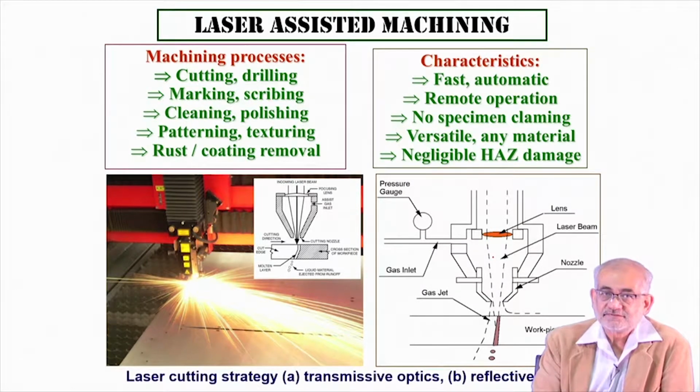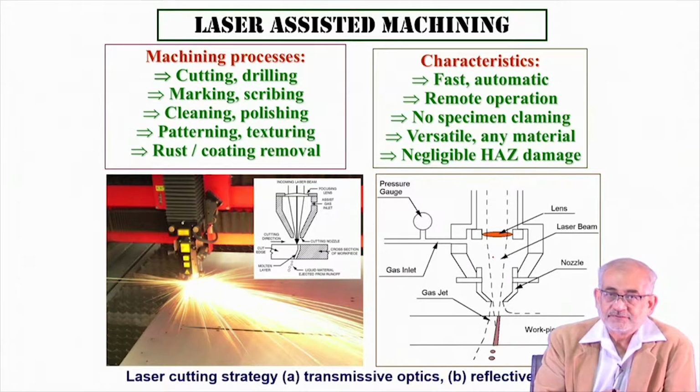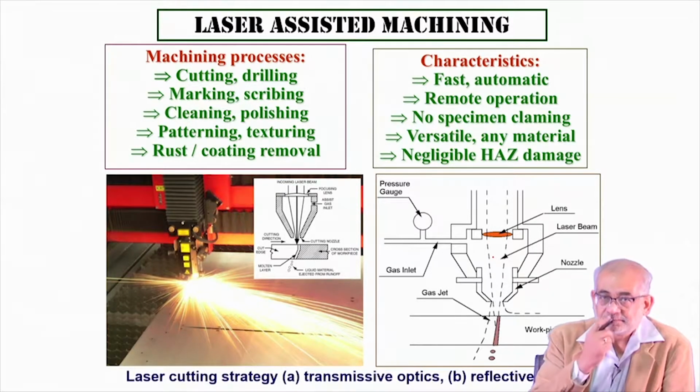When it crosses the vaporization temperature, you immediately convert the solid into vapor. This can be done purely by heating, or in some cases with shroud gases, but in some cases you can use an active carrier gas which could be oxygen. During heating it will also allow oxidation, and in the process it will vaporize very easily.